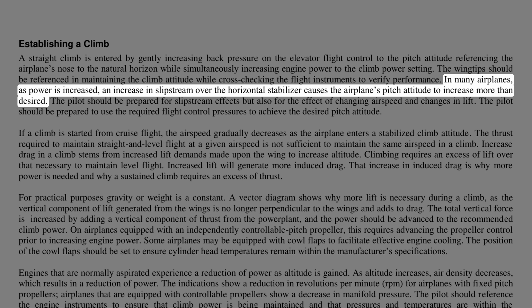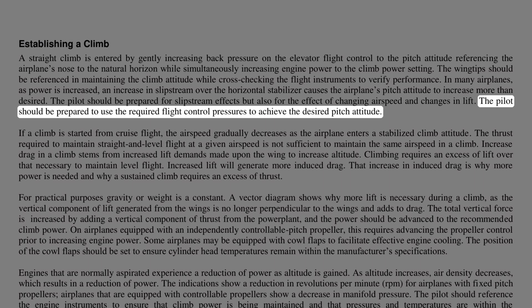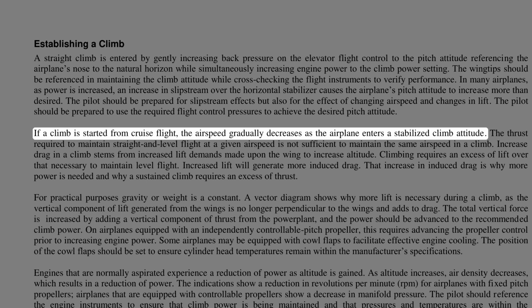In many airplanes, as power is increased, an increase in slipstream over the horizontal stabilizer causes the airplane's pitch attitude to increase more than desired. The pilot should be prepared for slipstream effects but also for the effect of changing airspeed and changes in lift. The pilot should be prepared to use the required flight control pressures to achieve the desired pitch attitude. If a climb is started from cruise flight, the airspeed gradually decreases as the airplane enters a stabilized climb attitude.